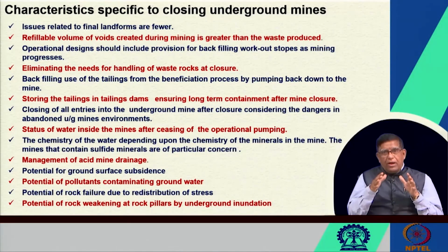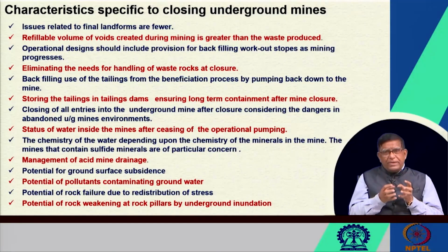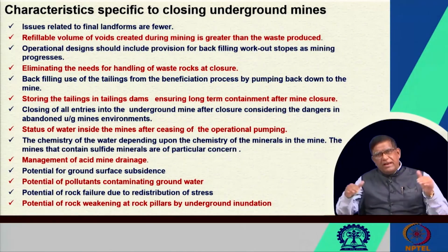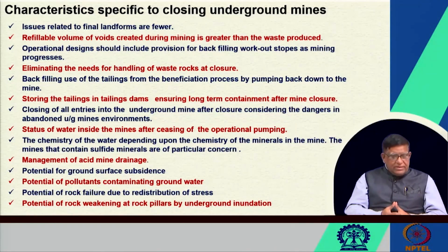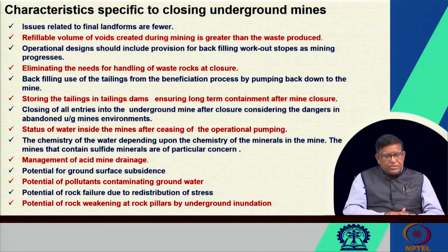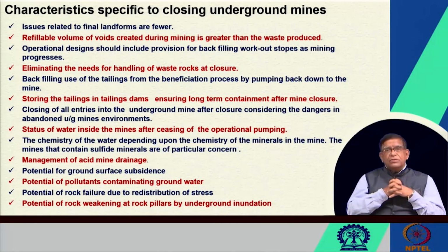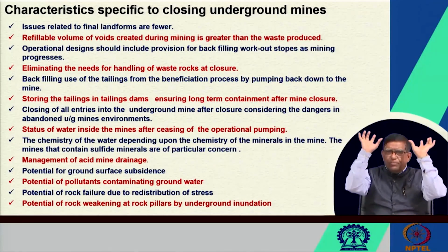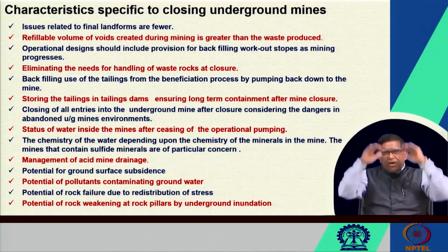Another thing is, as you have seen in the figure, when you have taken out the coal or the overburden, the stress distribution underground will be different. Some of the places will be highly stressed, and there the rock may fail, the supporting structure may fail, and then it collapses, and it can lead to problems at the surface also. Because of the water and all, the pillars can get weakened, and when they become weak, they collapse, they can no longer support the roof, and the whole strata comes down.